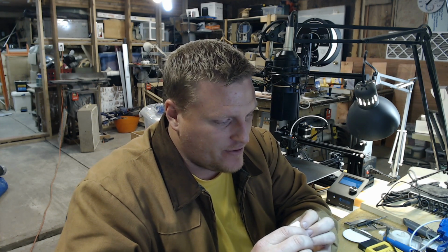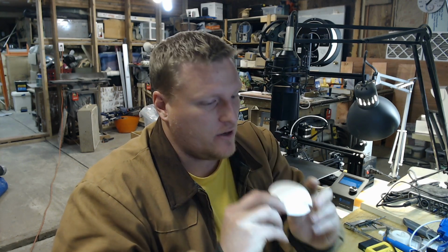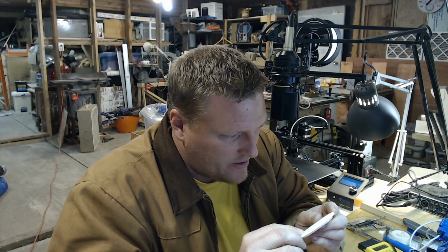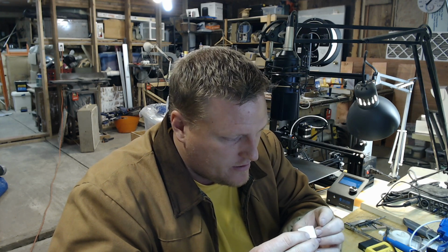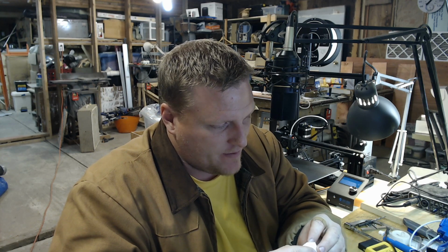Supplier could be producing inconsistent filament. So I just printed this also on it, and I don't see that. It looks fairly consistent. So I don't know. And yes, it could be that my stepper is skipping steps, but when it does that, I usually hear it because it jumps a significant amount. Since we're here, I'm just going to use the standard profile. We'll set it printing again. I don't know if it's going to finish by the time this stream is over.